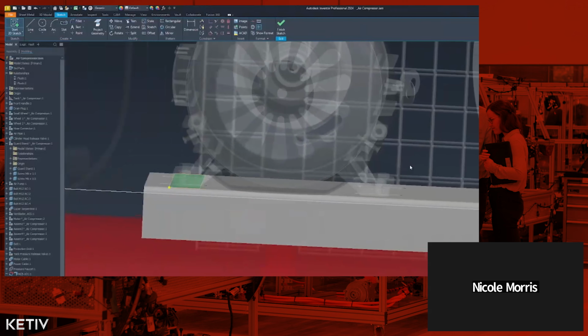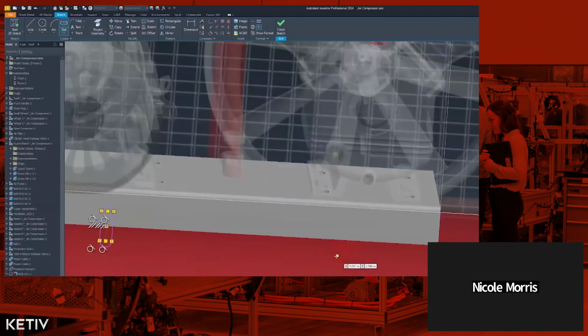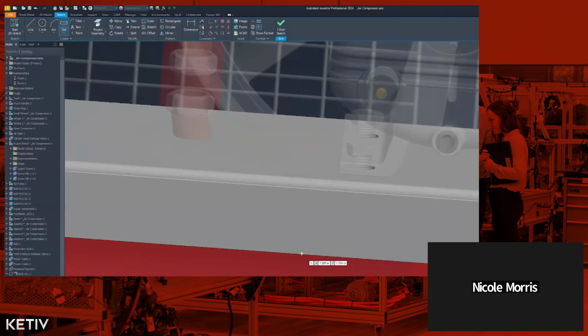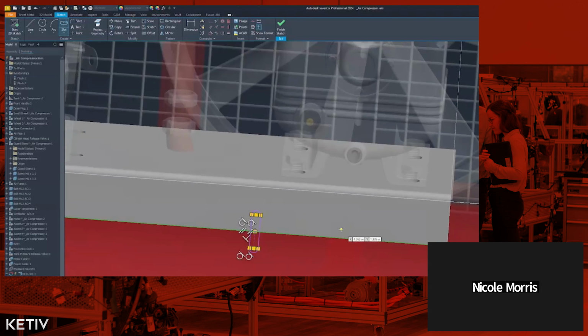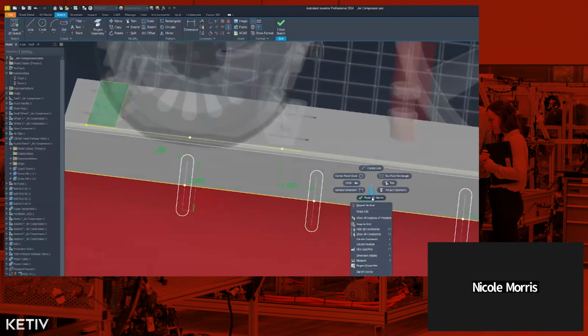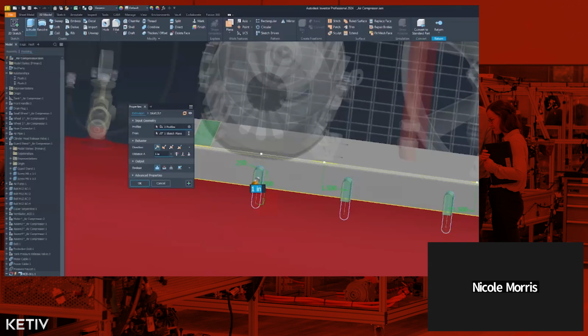And now he's going to create a sketch on the face of the flange. And he's using slots to create some vibration relief slots here, which Nicole nor Marco and I did not consider doing this at all. So Marco's background likely helped him out here and taught him that this would be necessary for a component like this. And he's now just extruding those out.